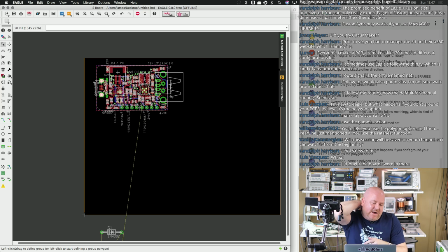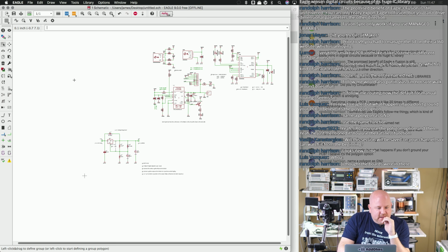Wow. Okay, this feature by itself, which I'm not sure if it's new to 9 or not, is something I can see use in, because especially for the first cut of a circuit board, I'm usually going from breadboard where I have things like Adafruit modules to a circuit board which starts to incorporate the Adafruit design into my design. And so a first step might actually be, let me just copy their exact circuit and then validate that I've got all the connections on the PCB right, and then optimize after that. So I really like that. That's pretty cool. Okay. All right.